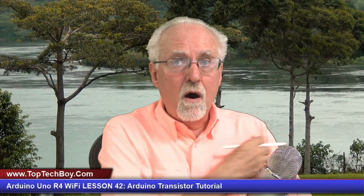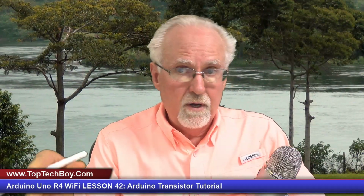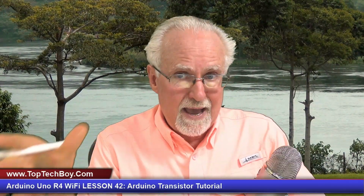Let's talk about what I am going to teach you today. I'm going to give you a tutorial of how to incorporate a transistor into your Arduino project. Now, why am I doing this? When do you need to use a transistor? You need to use a transistor when you need to turn on or off a component that draws a lot of current or uses a lot of power. You can't power those using your GPIO pins, so you need to incorporate a transistor.